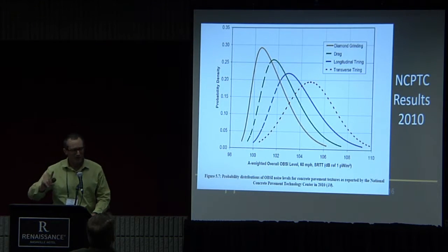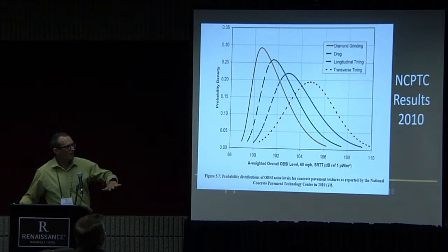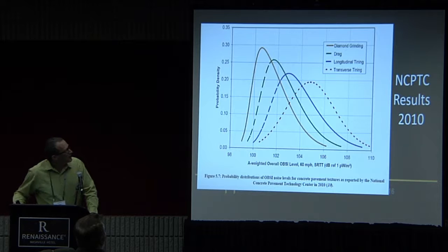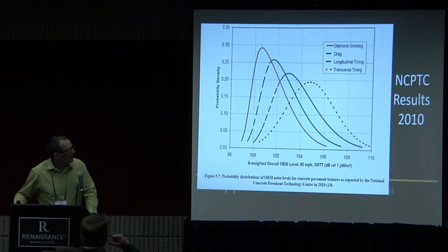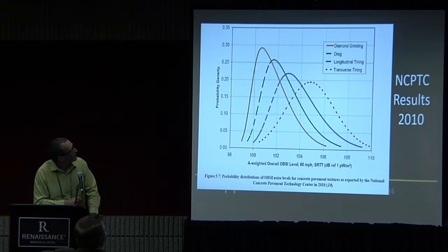Quieter, not quiet. We always say quieter pavements, not quiet pavements. Pavements are still noisy. So this is some work from the National Concrete Pavement Technology Center, our colleague Otto Rasmussen, and he looked at diamond grinding, burlap drag, longitudinal tining, and transverse tining.